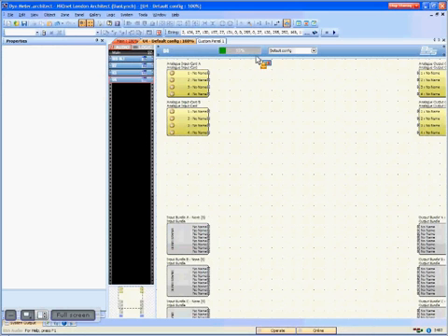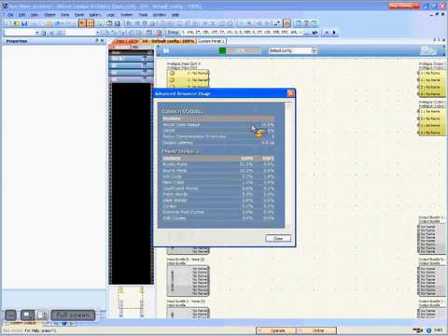What's that all about? Well, the worst case usage isn't necessarily all about processing objects. It's also about everything else down here. Cycles, there's our actual DSP cycles. We're actually sitting at about 5% right now, which is on one chip. So you call it 5.4%, but then you divide it between 2 chips to average it out, and the meter should really say 2.7% right now, not 15%.